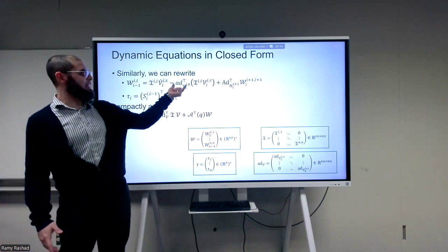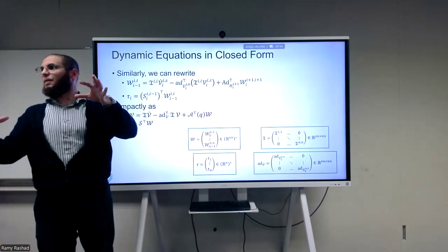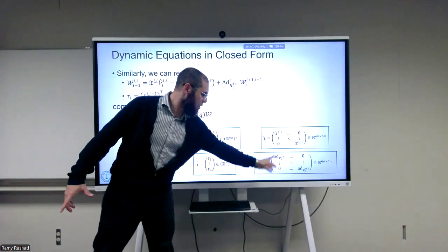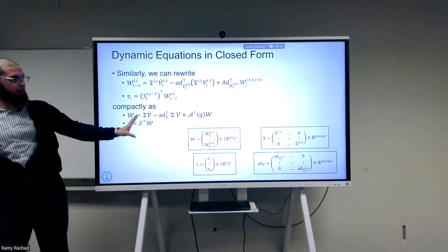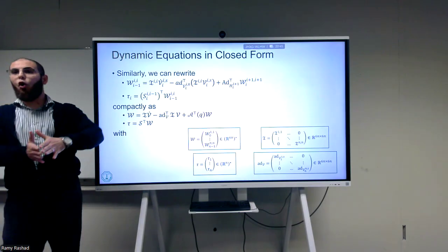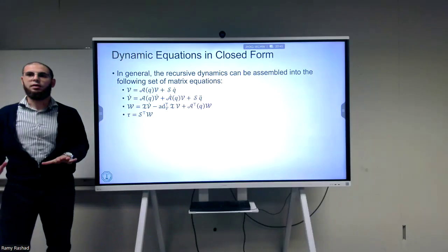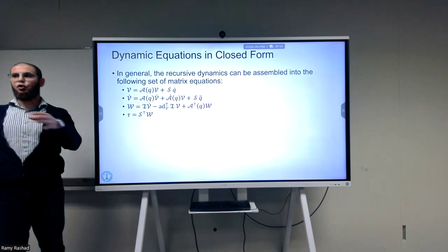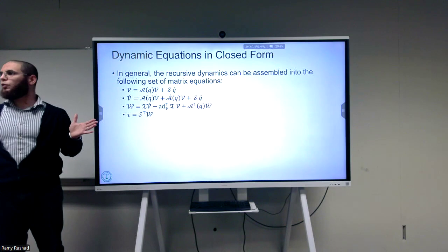And we're left with this adjoint transpose. This adjoint transpose of V is actually a 6 by 6 matrix. If I also concatenate them in this way, I can make one big Ad V matrix, which means that I can write these two as this. So what I did now is that I took all of these recursive equations and put them into these four sets of equations. Make sense? If you know how to do matrix manipulation, now you can easily follow from here.